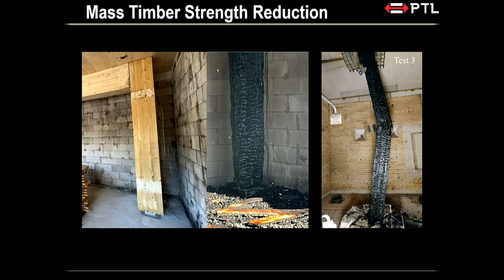So if you pay attention to some of the compartment fire photos that I've shown you, you will see hot gas coming out at the top of the opening, right? And fresh air is coming in at the bottom, right at the interface, where you have a lot of potentially unburned fuel going out and fresh air coming in, you get enhanced burning.